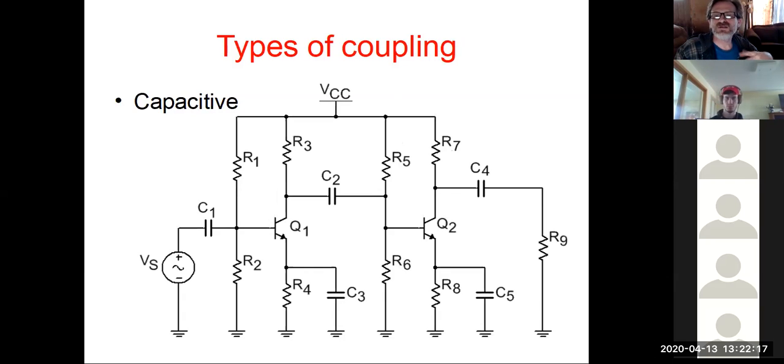And here's where I was talking about where we've seen the capacitive coupling, where if you notice, there's literally 2 bias circuits with this. So we have a voltage divider on the left and a voltage divider on the right. In between the two, you'll see C2, and there's our capacitive filter. So it tries to alleviate any type of feedback or noise from the first circuit to the second circuit. Doesn't always work, but it's a passive attempt, if you will.